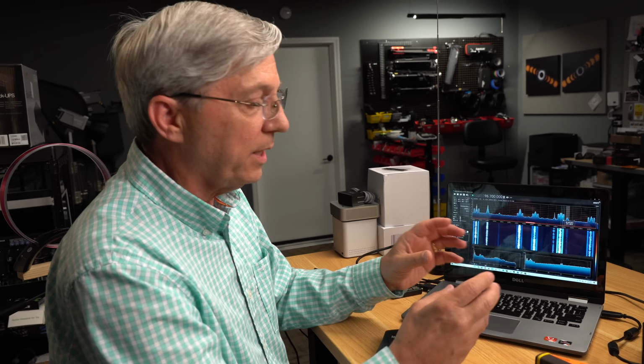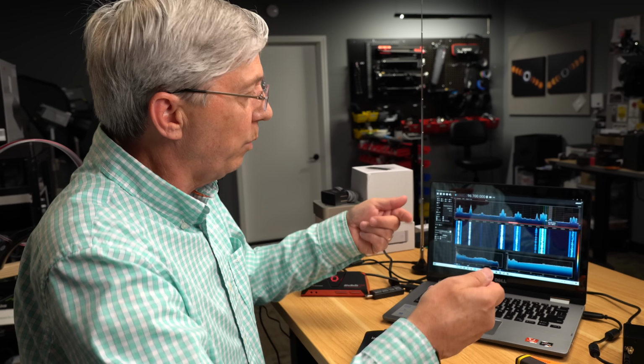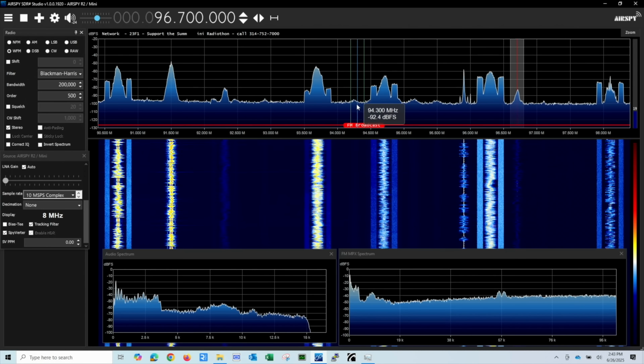So they build filters in, and they pre-distort the signal sometimes to get distortion in where it would want to pop up. It puts negative power into that area. But you can see here, I think this guy looks like he's got a little bit of regrowth above and below.